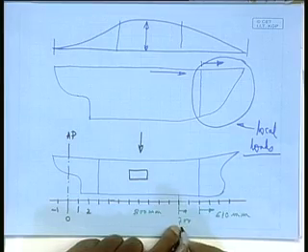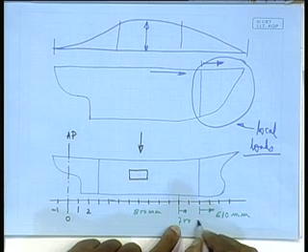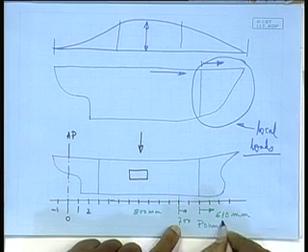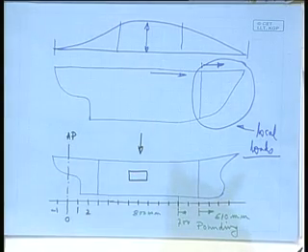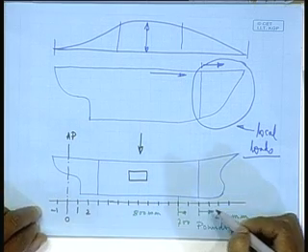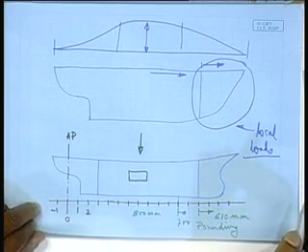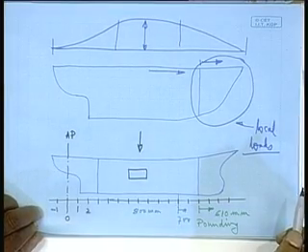Right. So, this zone is called pounding area. I mean, from where it is becoming 700, pounding, this area is called pounding, means as if it is pounding on the water surface, the slamming, right. Thereby you have lesser. So, that is one of the aspects, that forward of fore peak bulkhead, your frame spacing has to be reduced to 610 maximum. It can be less than that, but cannot be more than that.